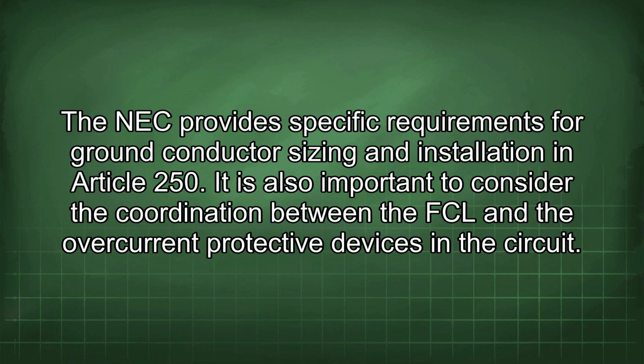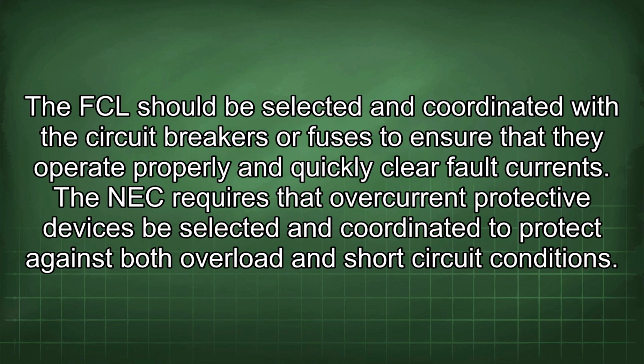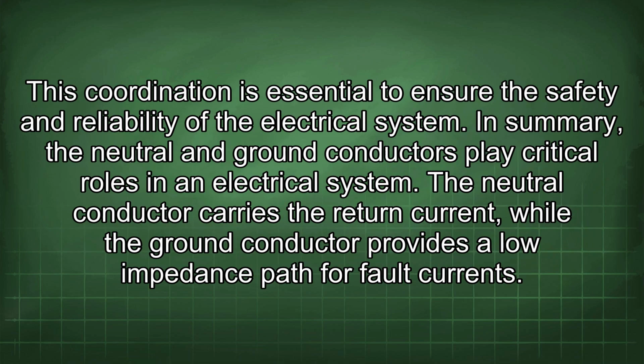It is also important to consider the coordination between the FCL and the overcurrent protective devices in the circuit. The FCL should be selected and coordinated with the circuit breakers or fuses to ensure that they operate properly and quickly clear fault currents. The NEC requires that overcurrent protective devices be selected and coordinated to protect against both overload and short circuit conditions. This coordination is essential to ensure the safety and reliability of the electrical system.